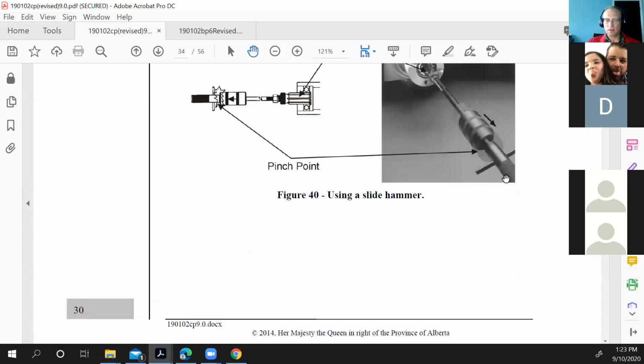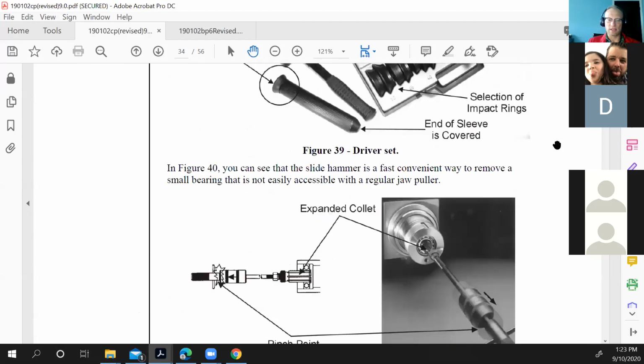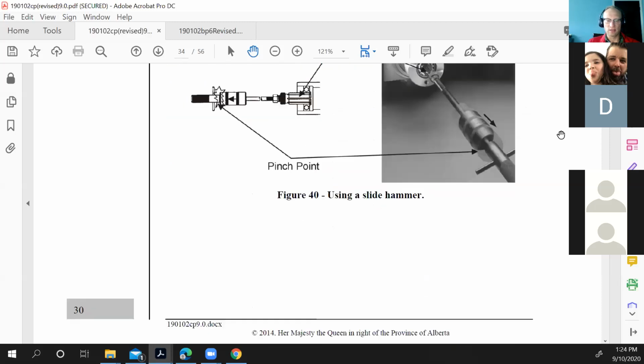For us, a lot of the seals that we're going to end up seeing are the larger Stemco seal drivers, okay? The company gives them to shops typically for free, and just make sure you pick the correct one when you're installing the seal.